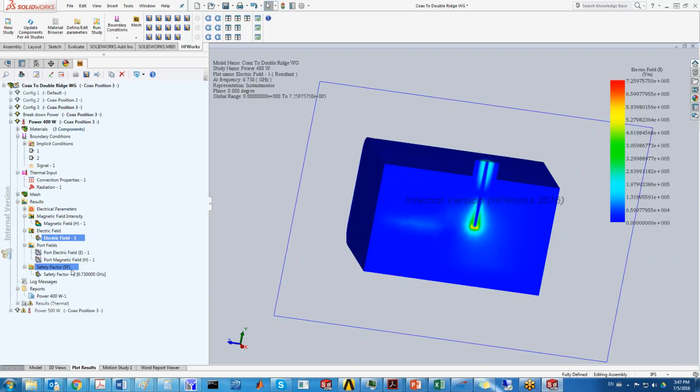So the rest of it, how to import it and what to do with it, is a challenge, particularly because the mesh is not the same. So there has to be some interpolation. If we give you different XYZ coordinates of our mesh from the SolidWorks mesh, then something has to be done there. It would be easier if we had more APIs and an automated process, and I think when users put pressure on SolidWorks, there could be some movement there. Let's hope that happens, and they contact SolidWorks for that.